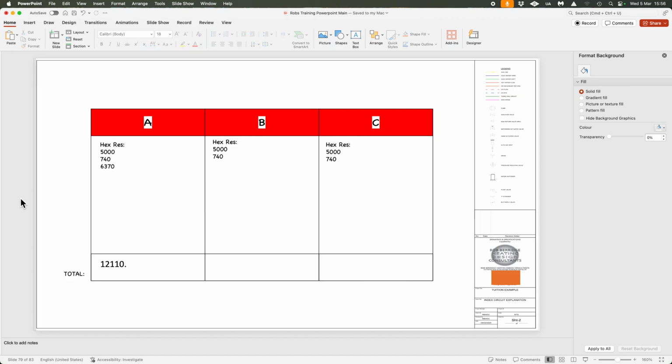And remember, one of the smallest pumps we can get is 50 kPa or 40 kPa. You'll find that a lot of heat pumps actually will have a much higher kPa rating within the heat pump itself, and it's more like going to be something like a 100 kPa, or certainly an 80 kPa or something along those lines. I've actually seen them at 120 kPa, which is 12 meters of head, or 120,000 pascals. And this is something that we need to get our heads around and understand why people are oversizing pumps way too much. Now we've proven that with a heat loss of that bedroom of 380 watts, I think it was, something along those lines.